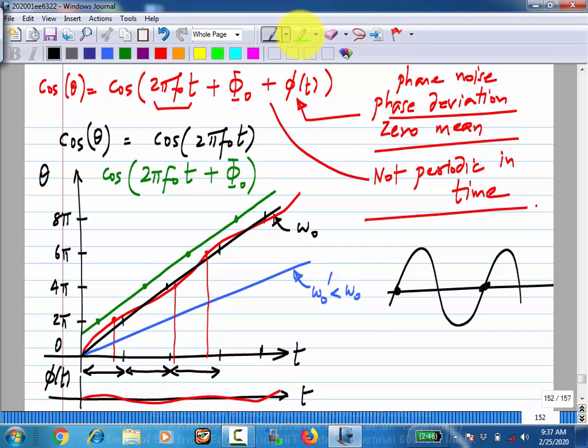Essentially, each period of the data, each symbol interval, should also be constant, so you can represent the ideal data phase as marching off as a straight line. Because random data will only have half the transitions, you are not sampling at every one of these instants; you omit some samples, that's all there is to it. Otherwise this picture applies even to data. Is this fine?